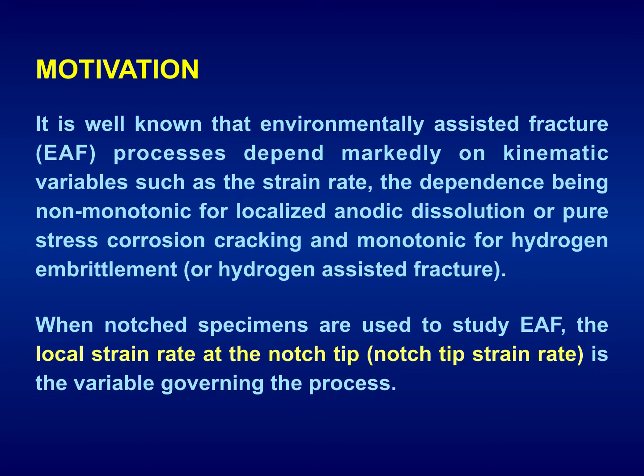The motivation of this work. It is well known that environmental assisted fracture (EAF) processes depend markedly on kinematic variables such as the strain rate, the dependence being non-monotonic for localized anodic dissolution or pure stress corrosion cracking, and monotonic for hydrogen embrittlement or hydrogen-assisted fracture. When notched specimens are used to study environmental assisted fracture, the local strain rate at the notch tip is the variable governing the process.